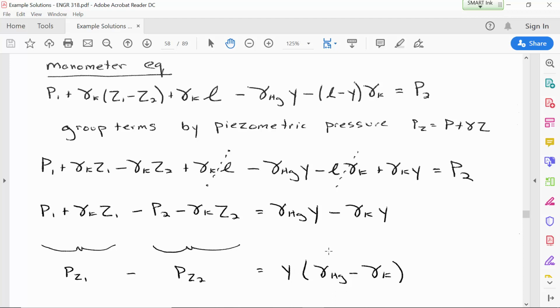Now, when we used differential manometers previously, the differential manometer was connected to 2 different openings in the same pipe, an upstream opening and a downstream opening. So it was a little bit different than here, where it's just connected to the pitot tube. In that previous case, the downstream liquid level was higher because the pressure was lower.